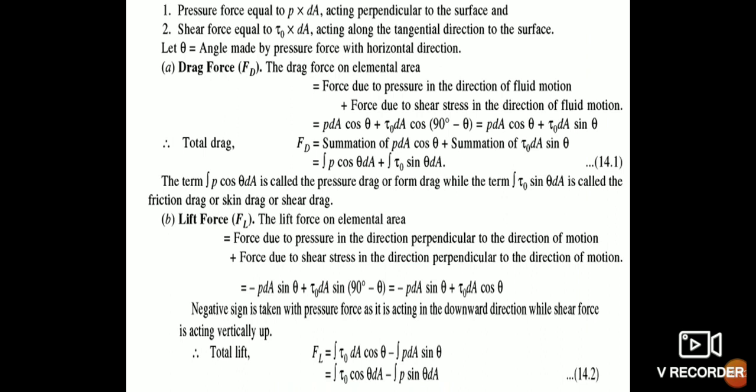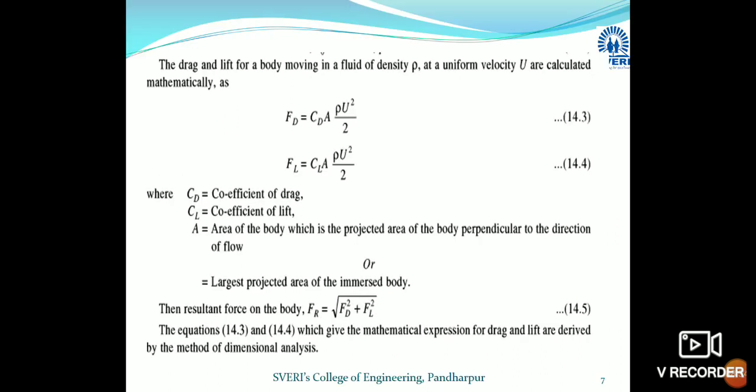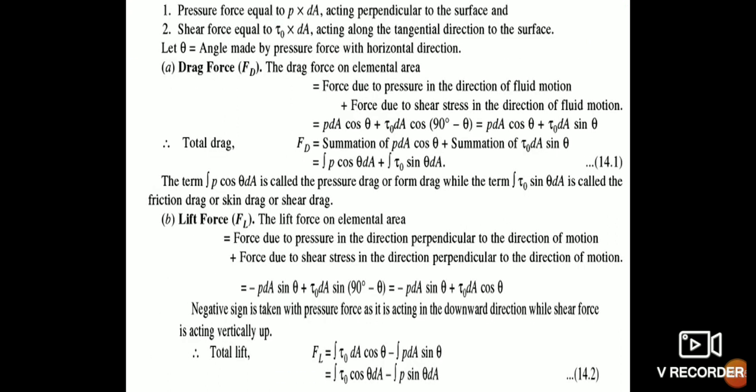Okay, now I told you the first force is the pressure force, equal to PdA, acting perpendicular to the surface. Now this PdA is acting in the direction of flow. Here again one consideration: the forces acting in the direction of motion are considered positive, and the forces acting in the opposite direction of motion are considered negative.